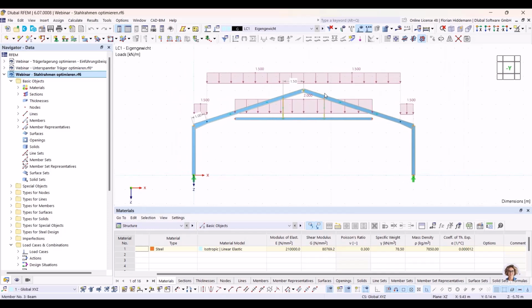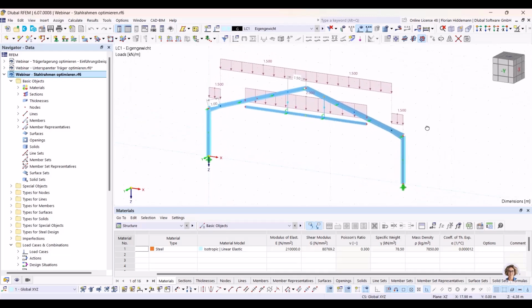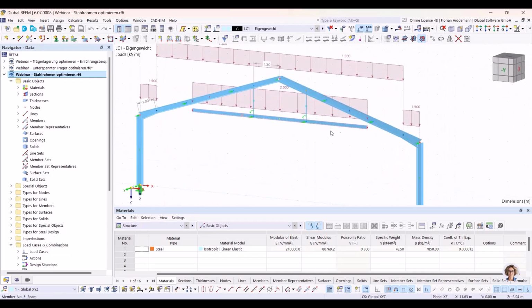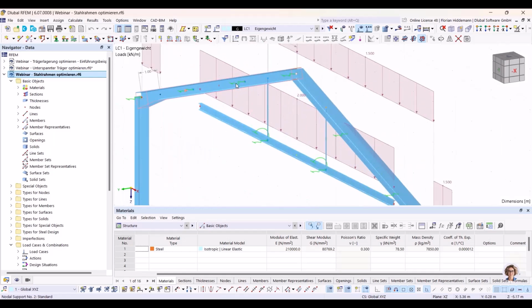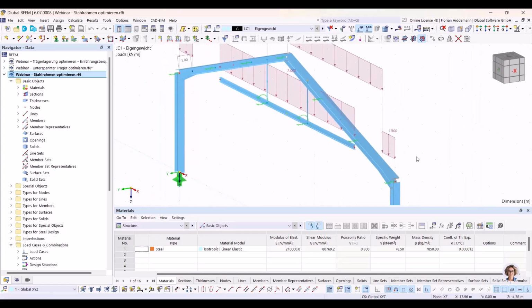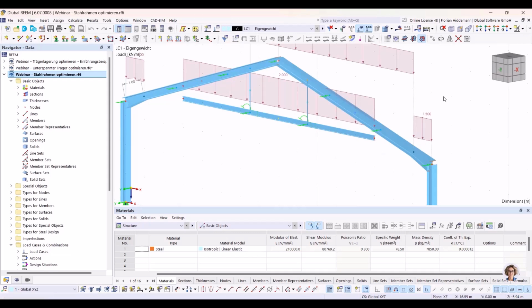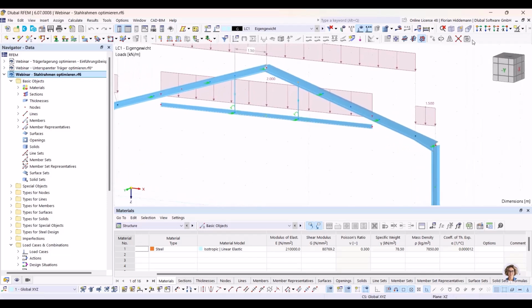So I used a very close approach to the other model. I only modeled here a 2D frame and defined here some spring stiffnesses in the out of plane direction to hold the model and to stabilize it from a numerical point of view. This is simulating what you would have in a real construction as your three-dimensional stiffness for the system.